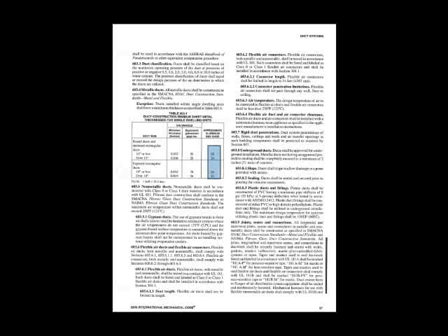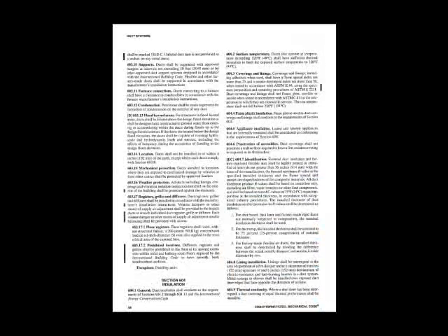Non-metal duct is discussed. Flexible air connectors are ducts. It talks about duct sealing for underground ducts, and all other joints, seams, and connections. It talks about the material you can use. It talks about duct supports in 603.10, not exceeding 10 feet apart, and approved hangers, again from the SMACNA standards. It talks about mechanical protection, weather protection, and registers, grilles, and diffusers. This is all Section 603.